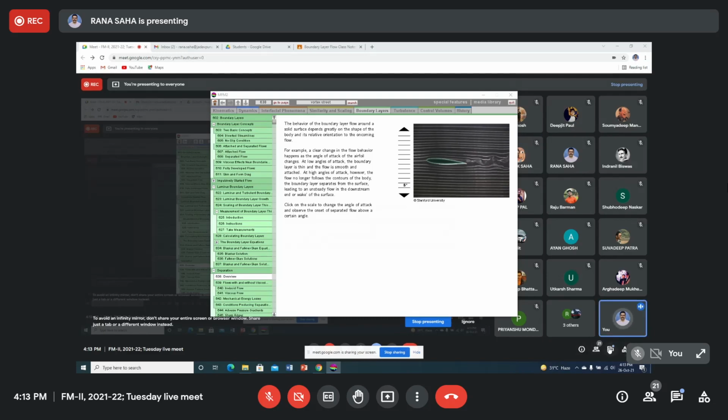You can have another source on the other side that also may cause flow reversal. But the one where you are having a body which is fixed in space, and a flow which is passing over the body. That is typically the one which is being done in experiments, in prototype in wind tunnel, where the body is fixed and you are actually supplying fluid at different velocities.